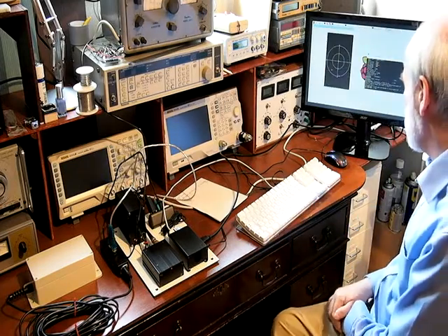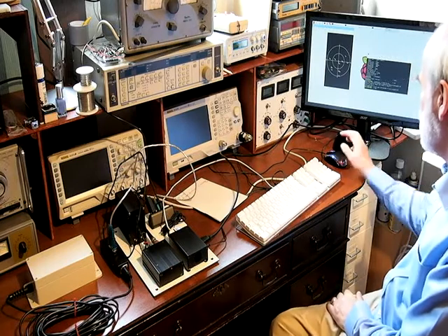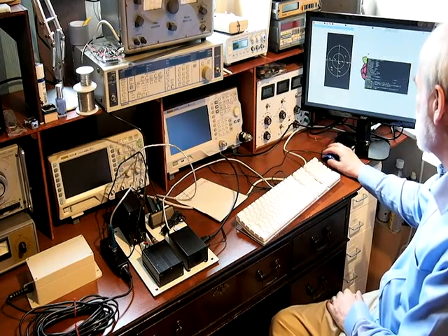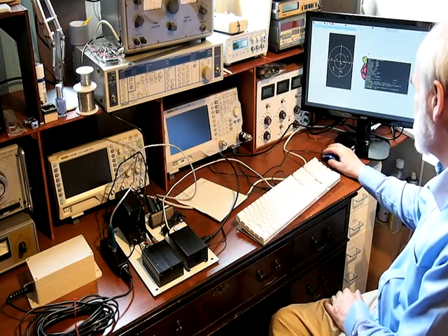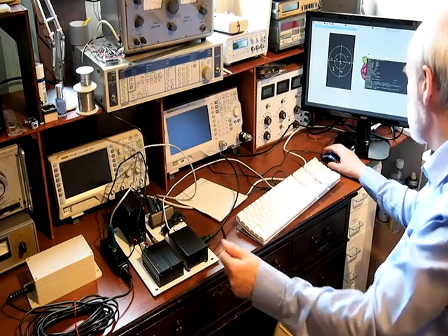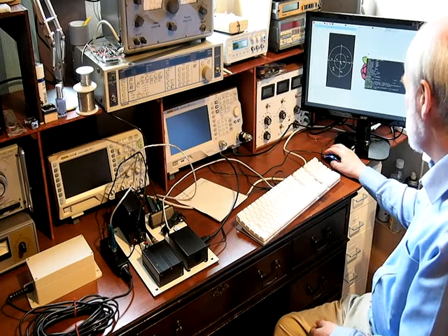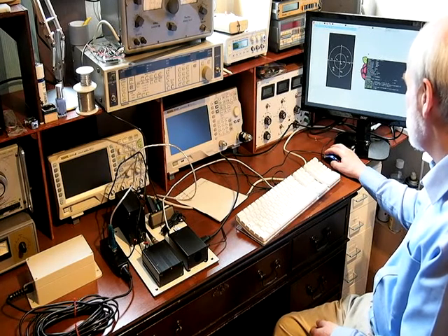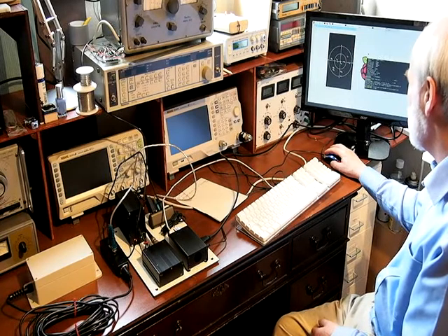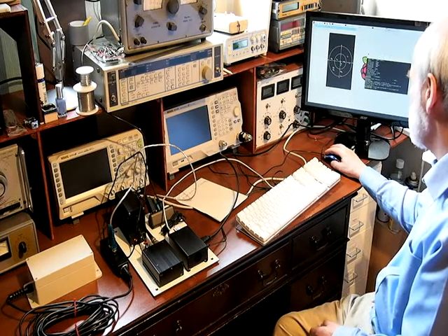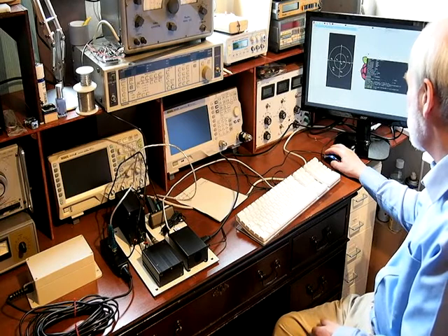This brings up a sky view in this X Windows pane of the satellites being received by the GPS receiver. And so here we have exactly overhead. Satellites in green have a signal to noise ratio of over 34 decibels.